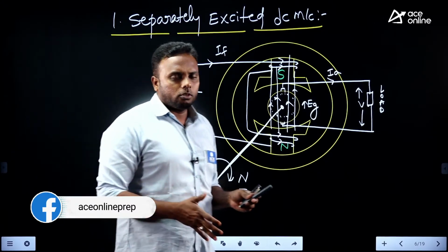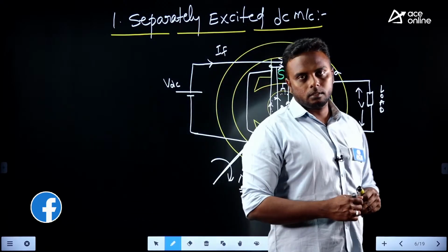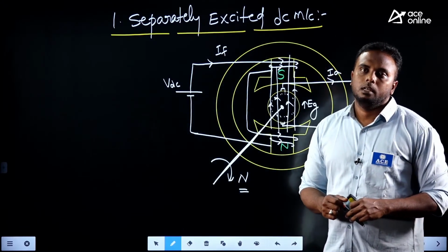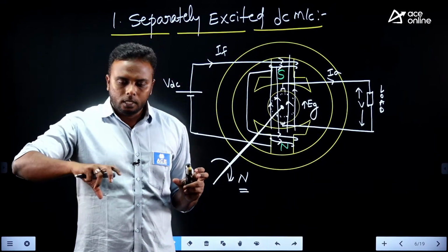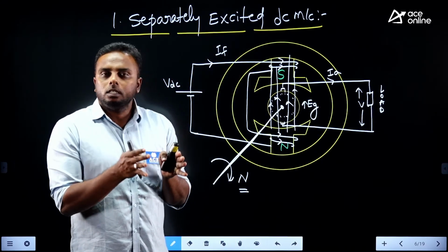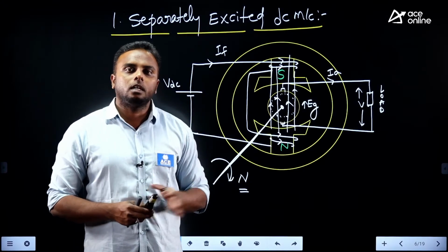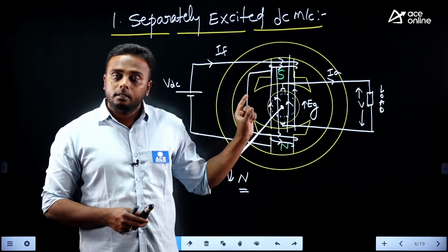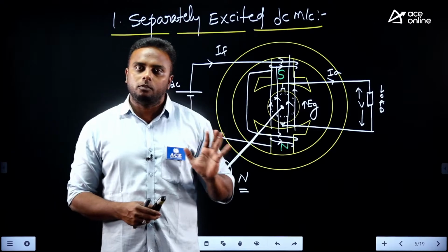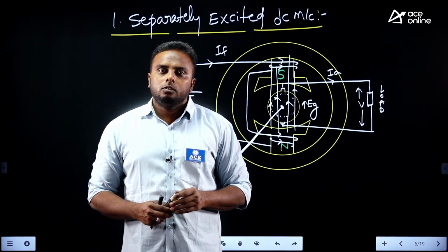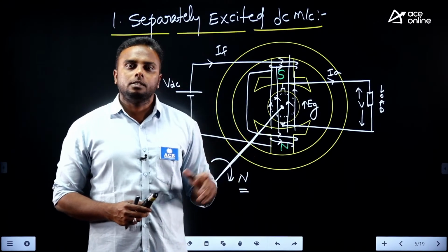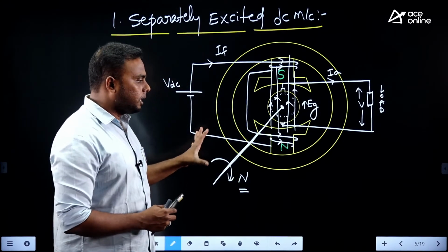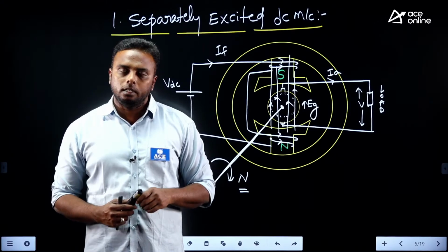In induction motors we generally do that blocked rotor test, but not in DC motors. So here in a DC motor, if you block the belt tightly, the rotor is blocked and won't rotate, then also back EMF is 0. At that time also very high current will flow in the armature. So these are the two conditions where armature current will be very high in DC motors: starting condition and blocked rotor condition.